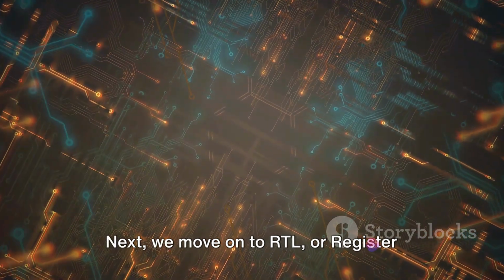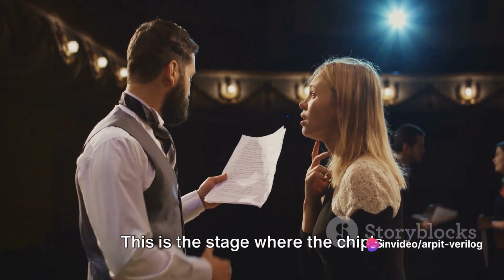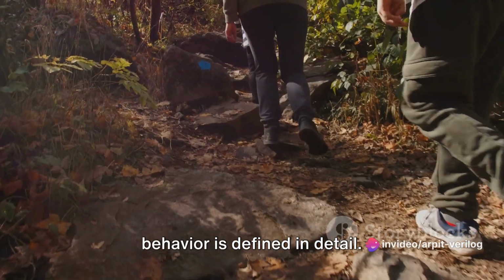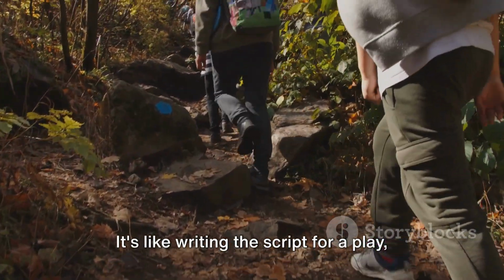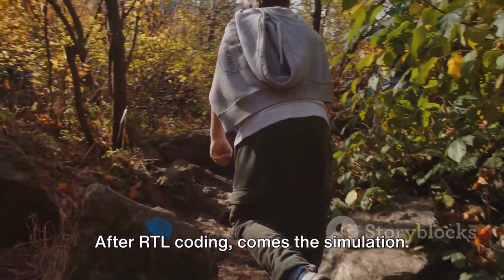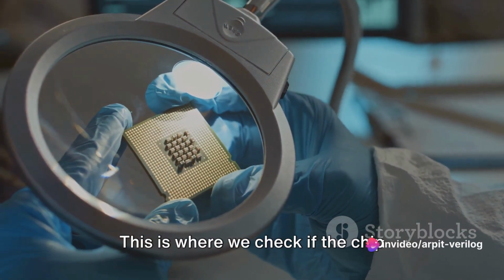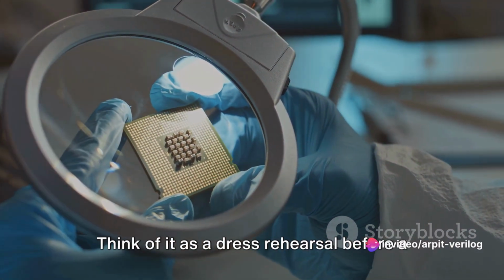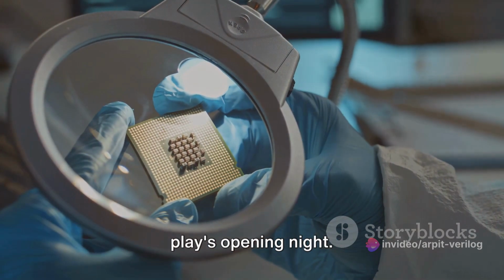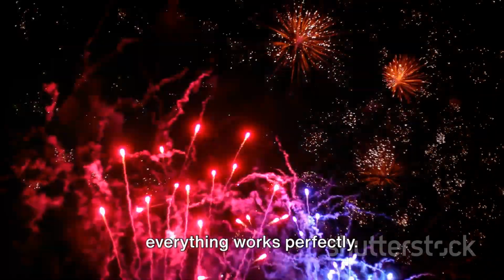Next, we move on to RTL, or Register Transfer Level Coding. This is the stage where the chip's behavior is defined in detail. It's like writing the script for a play, where each actor knows exactly what to do and when. After RTL coding comes the simulation. This is where we check if the chip behaves as expected. Think of it as a dress rehearsal before a play's opening night. It's a crucial step to ensure that everything works perfectly.